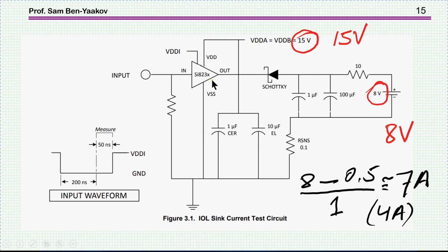So we know that for the high current type, the internal resistance here is 1 ohm. So approximately from this circuit, based on the 1 ohm, we should have expected up to 7 amps, sort of approaching 7 amp. And while the datasheet says that the typical value is 4 amp. So this is pretty consistent for the two types of parameters that are given.